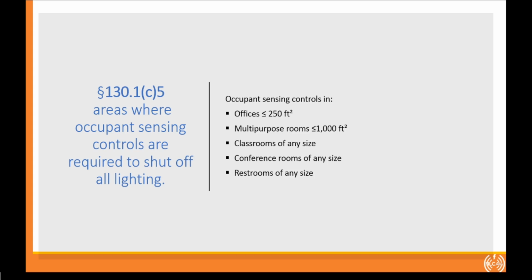Another mode that code will allow you to do is partial on. So you walk into the office, lights turn on, but they turn on partially, and it's got to be between a lighting power level of 50 to 70%. Okay, we're not talking about lighting level, we're talking about lighting power level between 50 to 70%. So you walk in, lights partially turn on, between 50 to 70% lighting power, still plenty of light in the space.